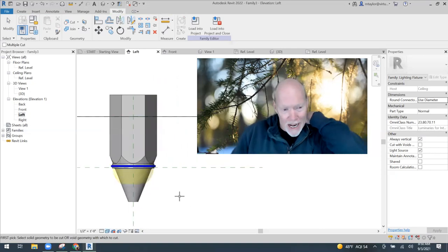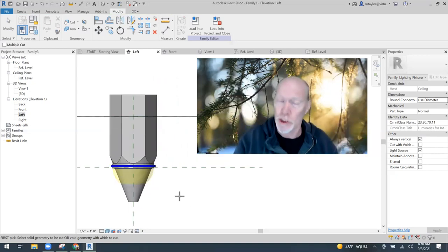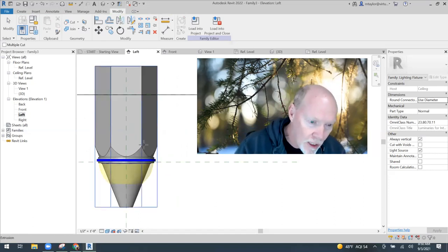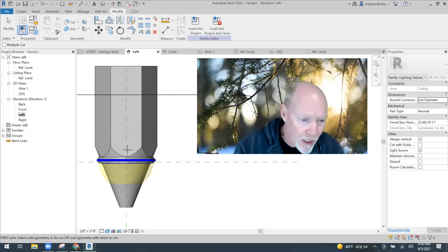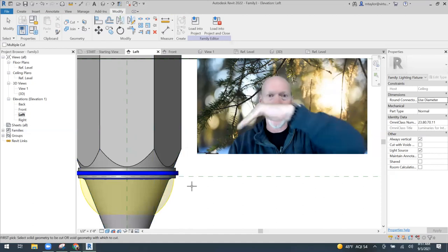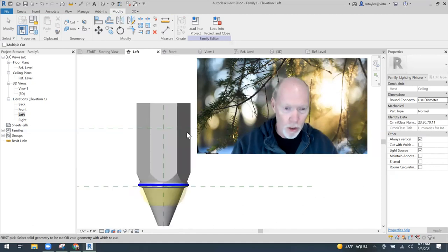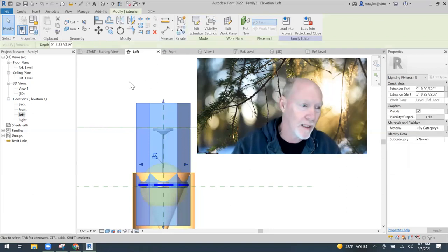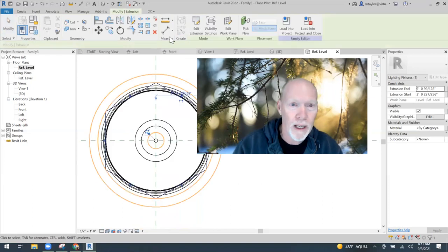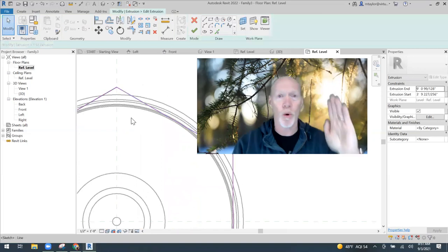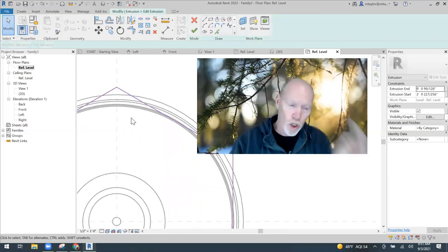Okay. So now that we've got this pencil shape in there, we can use these edges to create a sweep. Except I noticed that it comes to a tippy point, and I want those to be rounded at the top. So all I got to do is click on my pencil, basically, and edit it. I'm going to edit it from the top view, edit extrusion. And see, these can't be tippy points if I want it to round. I need to curve these off.